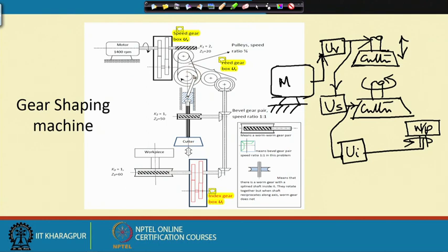Here there is a bifurcation, the power is taken out after the speed gearbox, and it travels, and this itself is called the feed gearbox. It passes through the feed gearbox and goes to the cutter once again, but now to rotate it. With this one you have bevel gears and a worm gear, and while it is moving up and down, it also rotates. How does it do it? With a splined shaft.